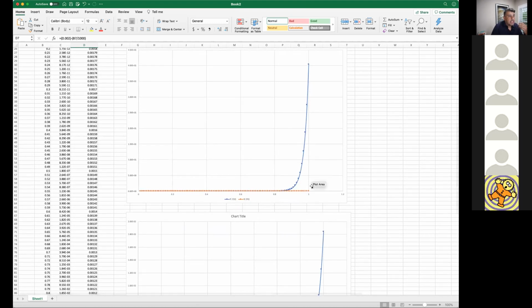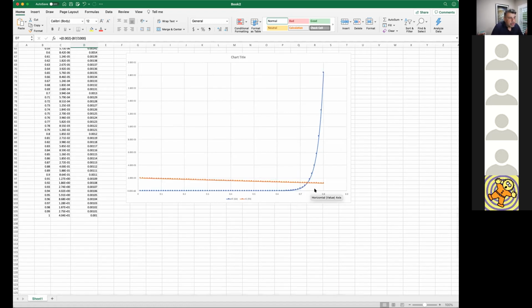Look at this guy, zoomed out a little bit at 1 volt. This is already at like 40 amps coming out of this transistor, which, unless you're making power circuits, ain't gonna happen, right? So these are reasonable estimates. That's why I'm saying the reasonable estimates for VBE are between 650 and 850, somewhere around here, because it just takes off like crazy after that, and before that you're just at very low currents.